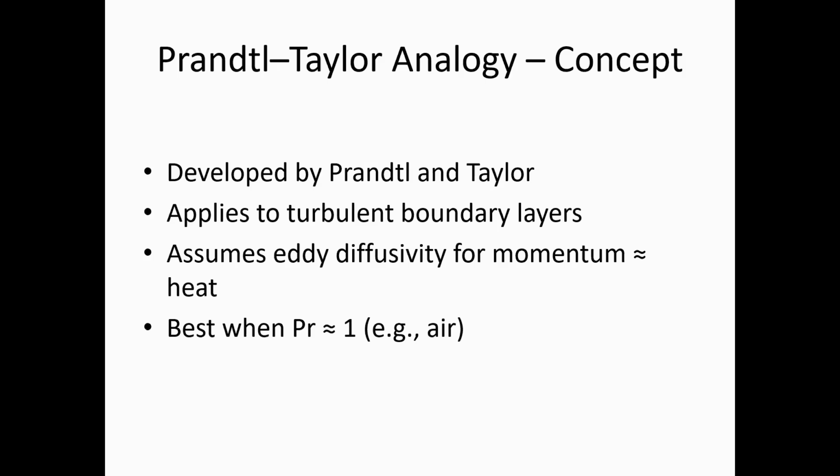This analogy was developed by Prandtl and Taylor. It applies to the turbulent boundary layer, and assumes that the eddy diffusivity of momentum is equivalent to that of heat. This analogy is best and perfect for a Prandtl number equal to 1, that is, air.